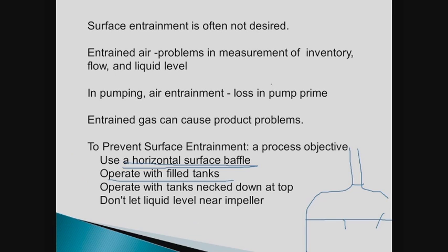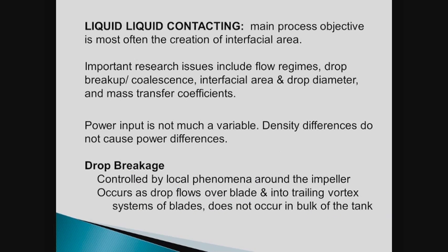So operate with full tanks. If I have a full tank, there is no surface, and as a result, there would be no surface entrainment. The other way is to have it neck down. This is the neck down. And don't have the liquid level near the impeller. Liquid level near an impeller is basically a splasher, so you don't want to necessarily have that situation happening.